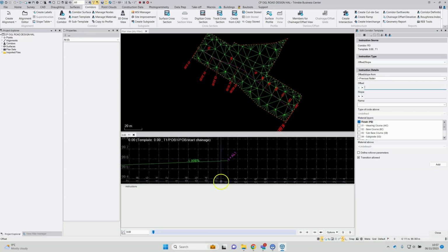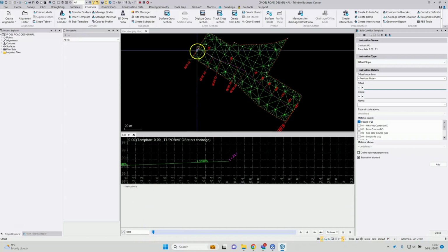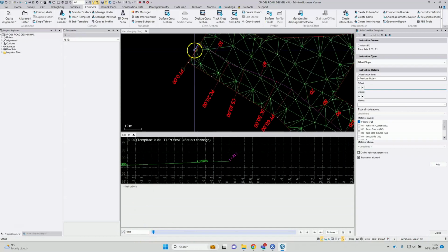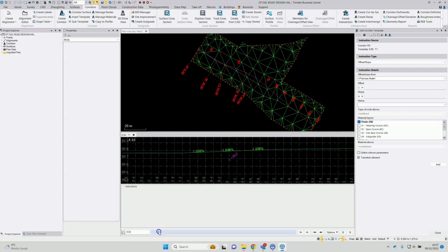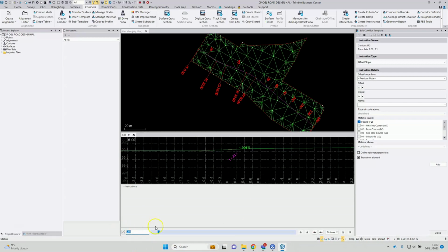It's always number 1. Instantly we're looking at chainage 0 here, which is only the start of the line, only partially on the surface model. If I move the chainage position along a bit, you can see the surface extending fully across, and we'll set it to chainage 5. So node 1 is the starting node where the alignment sits relative to the corridor. There are no other nodes in here yet from which to create the surfaces, but these are about to be entered.